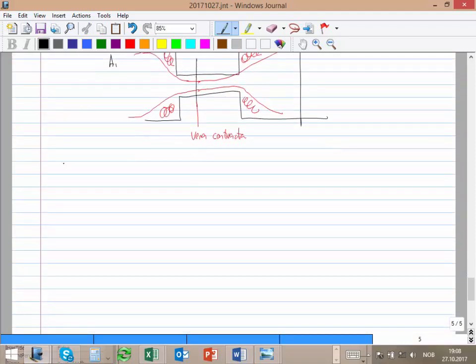What is the main function of the choke? It's just to drop the pressure. To drop the pressure is a different way of saying you want to dissipate a lot of energy in a very short, concentrated place. That means reducing the pressure, and you don't want it to go back up.